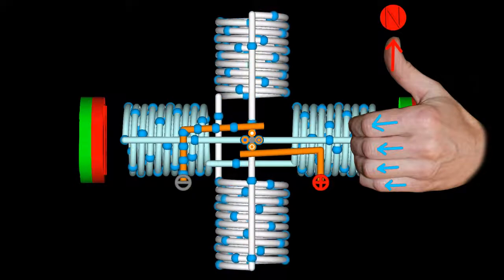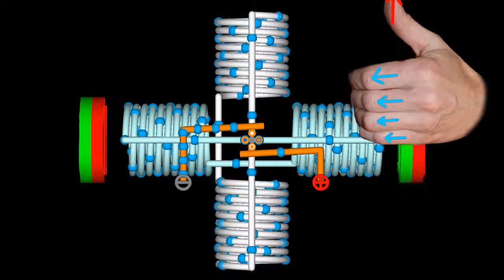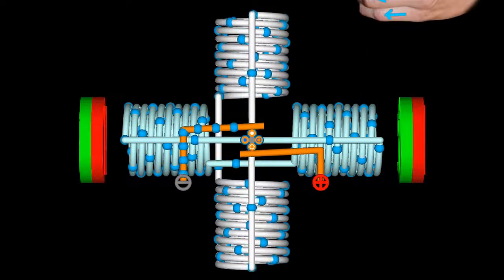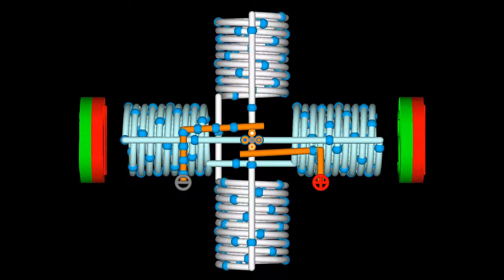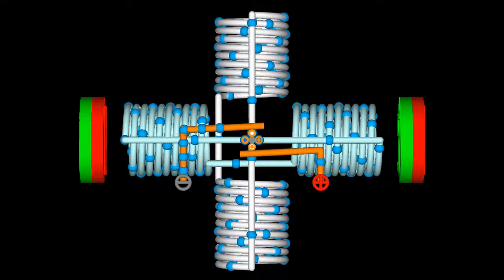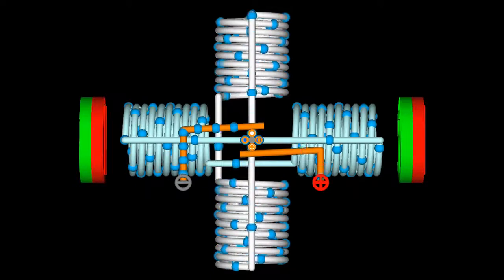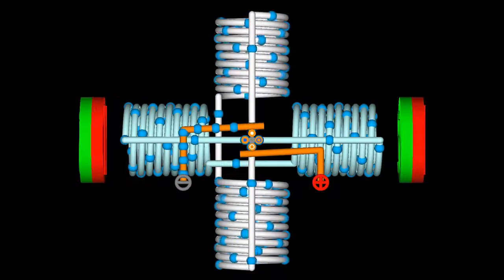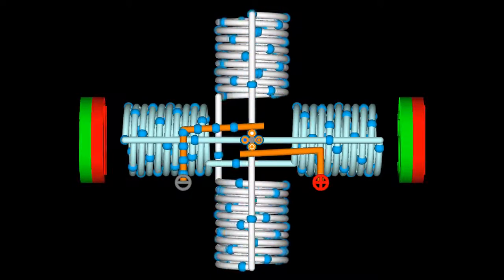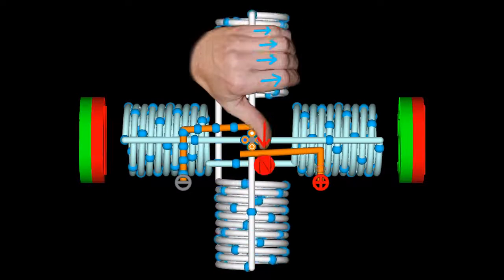When trying to grab the solenoid in such a way that your fingers point into the direction of electron movement, your thumb points to the magnetic north pole. Where is that pole? You are correct if your thought was downwards.